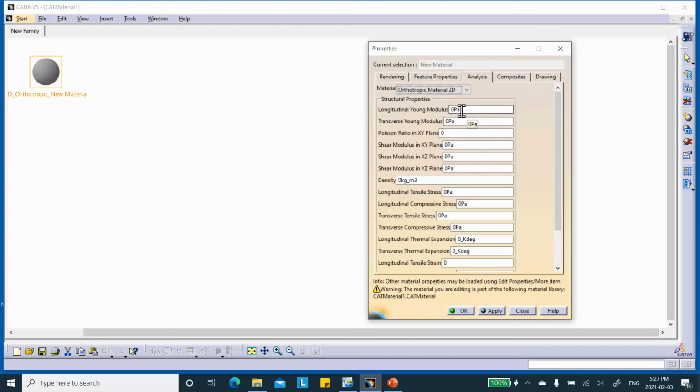But we're going to use exactly the same thing. Whatever I put for longitudinal in the other one, I'm going to put it right here. And I believe that was 20 point, bear with me for a second. Okay, so the same thing that I put in the Young's modulus for 3D, I'm going to put here. I think it was 20.1 GPa, big G, big PA.